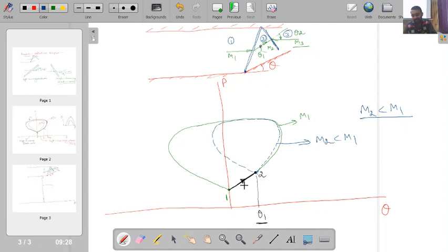Now you are correct. If you see this second wave, it was in this direction. We have already accounted for this because we started its pressure deflection diagram from a different vertex, which starts at theta 1. With reference to this, it is making an angle of theta 2, and this theta 2 is in the negative direction, and this is a right running wave. So here I am seeing the negative deflection.